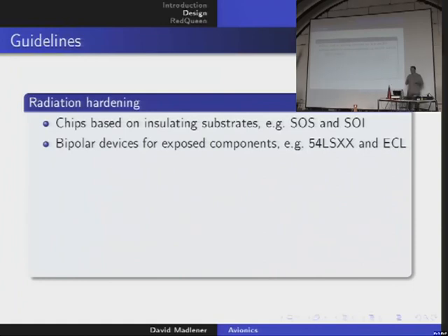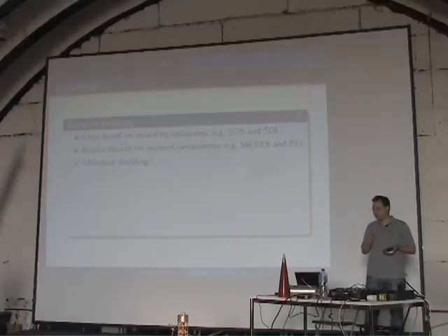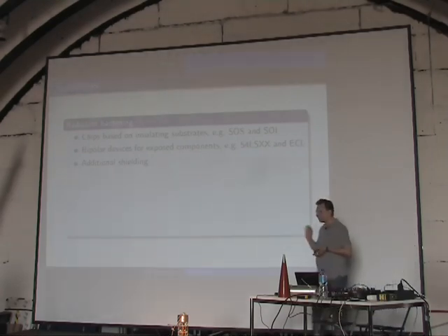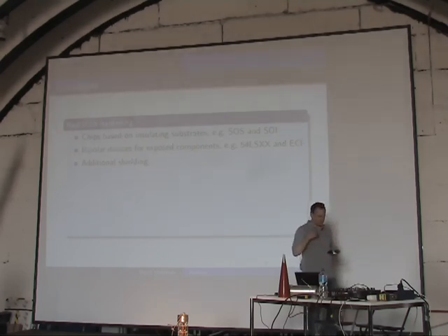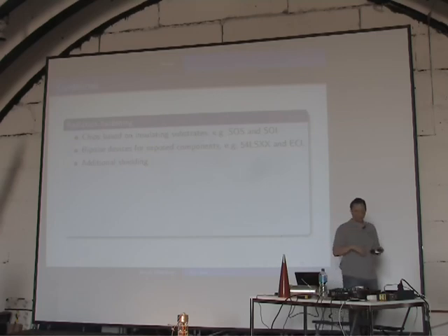So, of course, additional shielding helps. Putting something, an aluminum part of, let's say, 5 millimeters over it will help. The problem is, if you are in outer space where the cosmic background radiation comes, the really high energetic particles with 1 tera electron volt or something like that, then additional shielding can be bad, because the additional matter in front of your electronic devices is the material where these very high energetic particles can produce neutrons and so on.